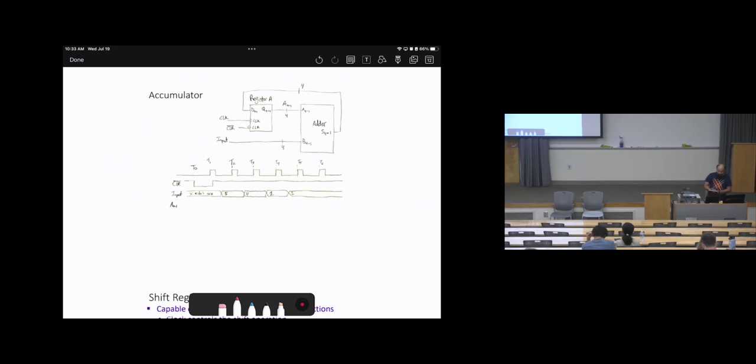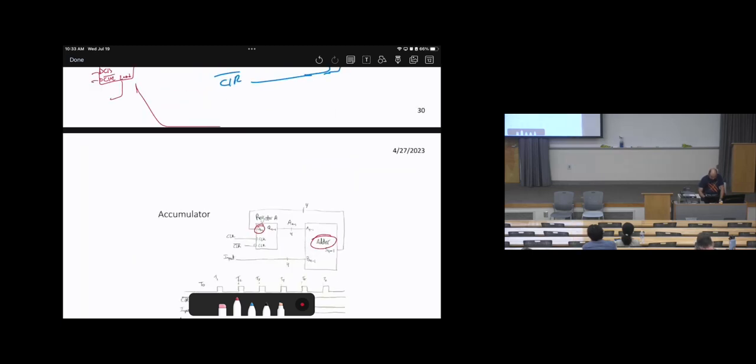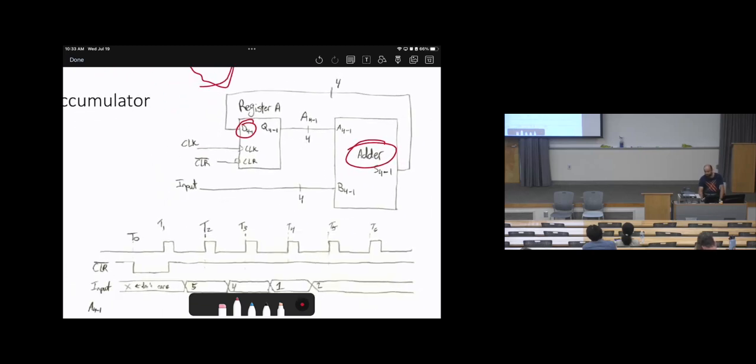There is some type of registers called an accumulator. That accumulator can be used to add some data, to store some data, or to count something and keep adding some numbers. Since there is addition, we have adders. This is the 4-bit register as I showed you here, connected to the 4-bit adder. Each output has 4 bits. There are inputs, a clock, a clear, and outputs.